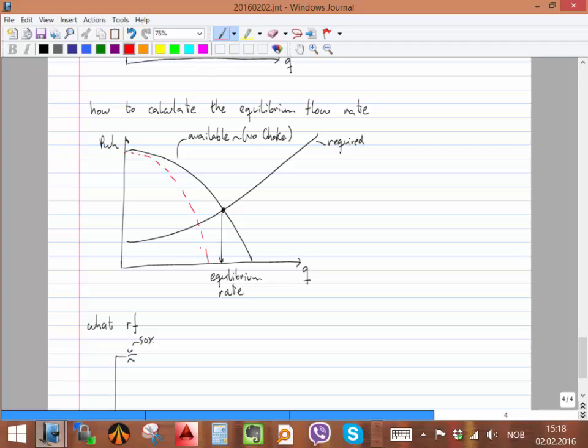One question: should the value at the origin change? That's when I shut in the well, leave it, and measure the pressure. Does that value change if I have a choke or not? No, because I have no flow. So that point stays the same. But if we have, for example, a 50% choke opening, now you see, okay, Bilal?